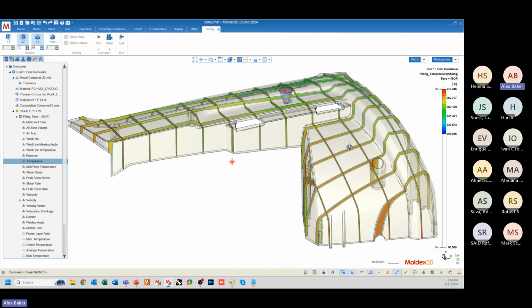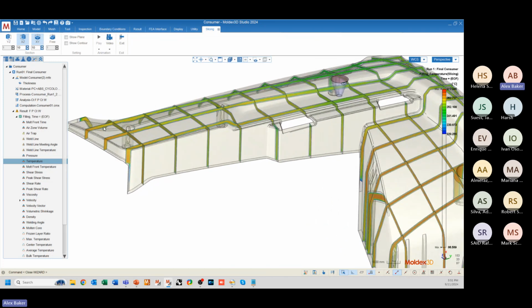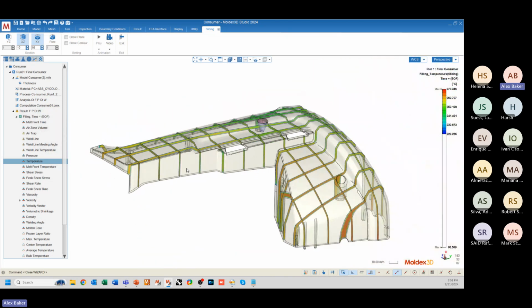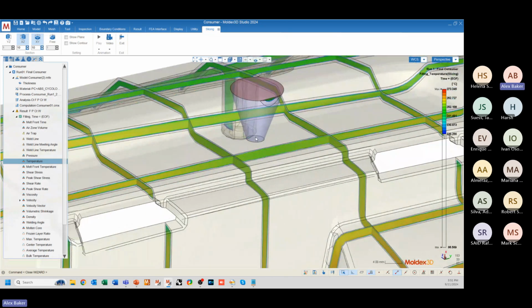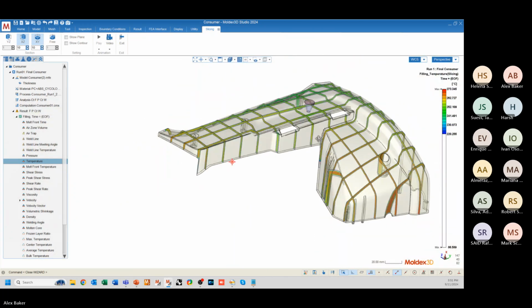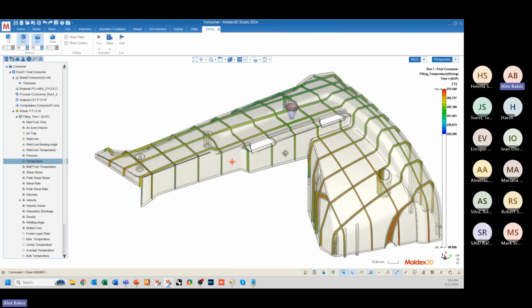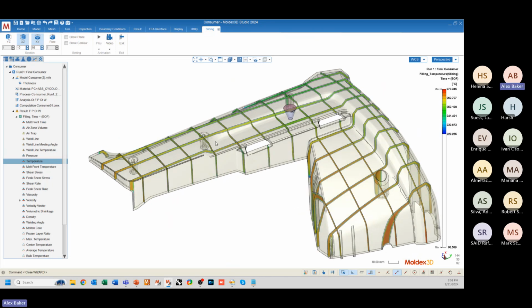And we can pretty obviously see from the slicing grid that the end of fill temperature distribution in the core of my geometry is hotter than my gate location, or the gate region. All right, so in this case, I would say that the shear heating effect, the heat generation created by the friction of the material, is greater than the heat that was released out into the mold.